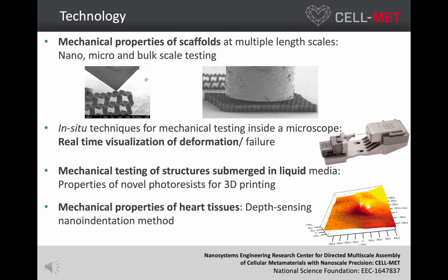In order to resolve these features, we perform in situ testing inside a high-resolution scanning electron microscope. During in situ testing, the deformation phenomena are captured in real time as the structure is subjected to mechanical loading. A mechanical stage is shown in the slide. This stage can be installed inside the microscope for performing in situ tests.